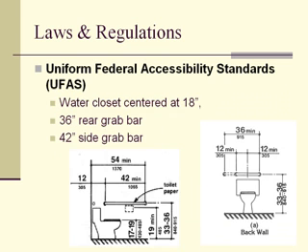Okay, another requirement, and this is one that we'll find throughout the facilities, is for the water closets. And this is actually a pretty tough standard to meet: they should be centered at 18 inches from the wall. Okay, and the height. Here we are looking at one of the water closets that can be in the common areas. In common areas, they are allowed to go between 17 inches to 19 inches above the floor to the top of the seat.